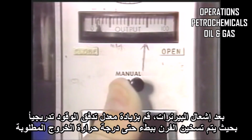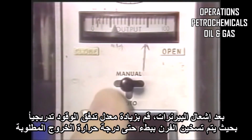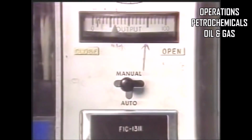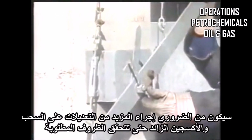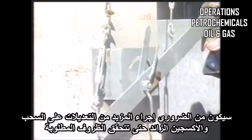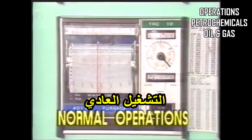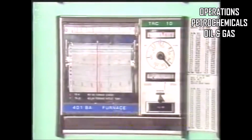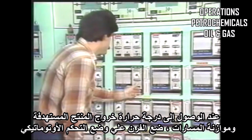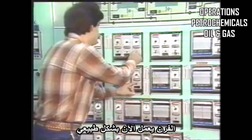After lighting the burners, gradually increase the fuel so that the furnace is slowly heated up to the desired outlet temperature. It'll be necessary to make further adjustments for draft and excess oxygen until the desired conditions are achieved. When the target outlet temperature is reached and the passes are balanced, place the controls on automatic. The furnace is now in normal operation.